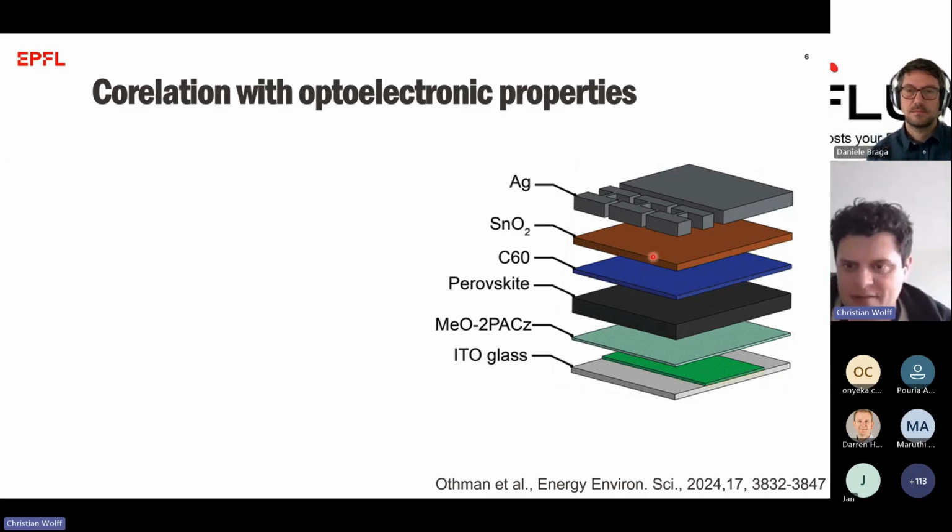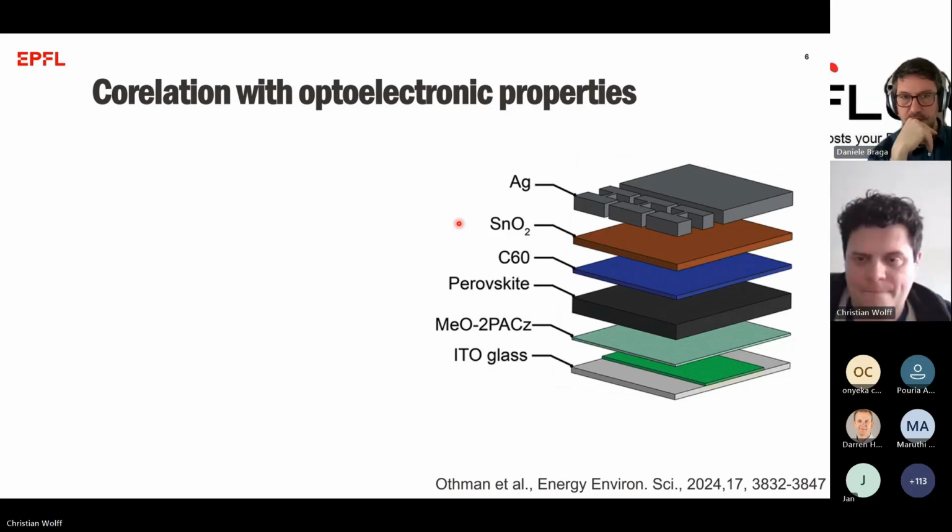So we would typically then sputter with a plasma or RF sputtering system that is relatively aggressive, a TCO on top, so it protects from sputter damage. You could also put BCP in between, which will help in stabilizing the interface between silver and C60. You can make devices even without that. They will work, they will be rectifying, but you will have slightly lower performance. So I would advise against that. Yeah. The reason being, BCP helps with modifying the work function of the electrode.